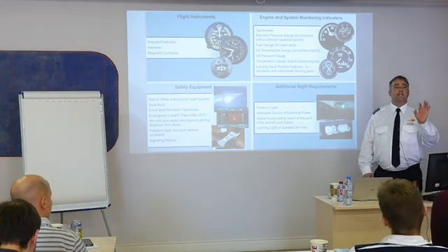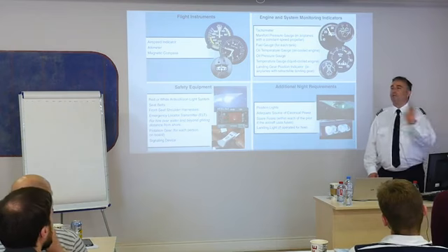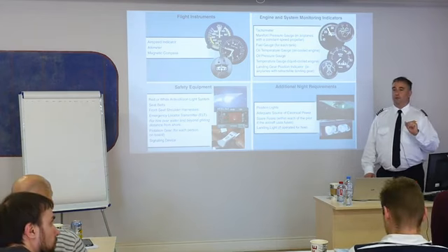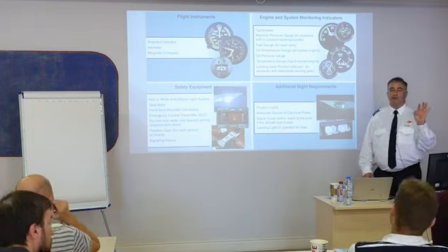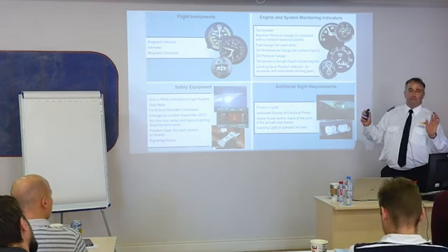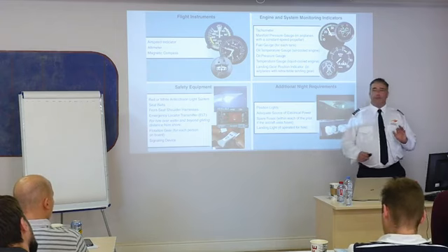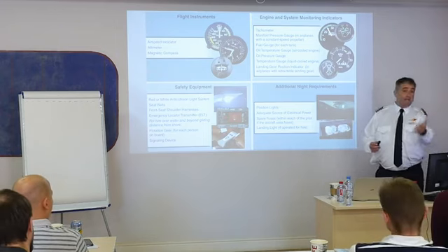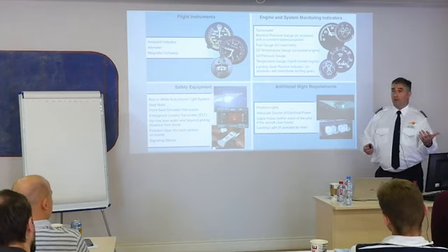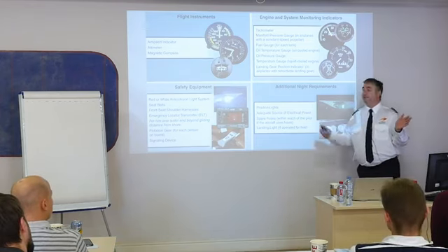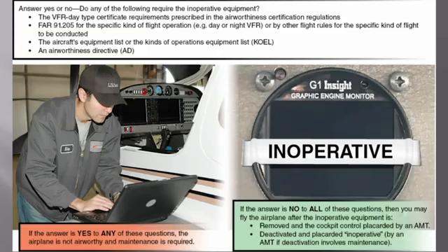I might have an ADF, navigation radio, that is not used very often by anybody in the United States, the Caribbean, South America, wherever. Okay? It's in the airplane. It doesn't work. I'm not going to cancel the flight because of that. But I still need to report it to maintenance. And it's supposed to have this label on it if it's not operating properly. It has to be placarded that it's not operating properly.